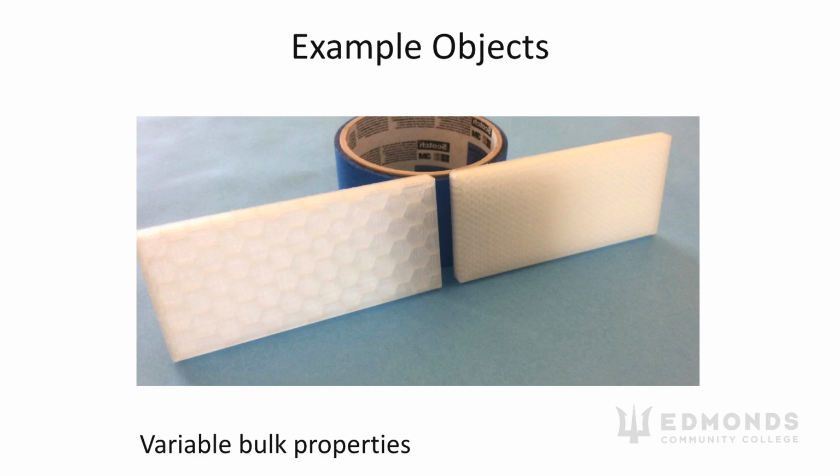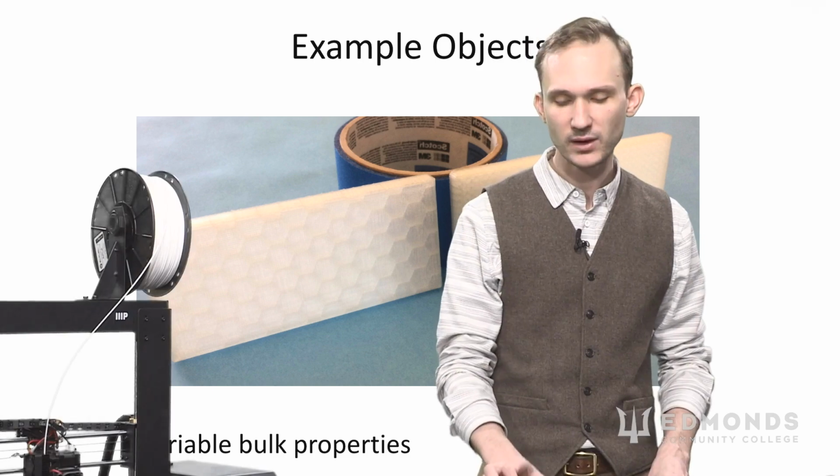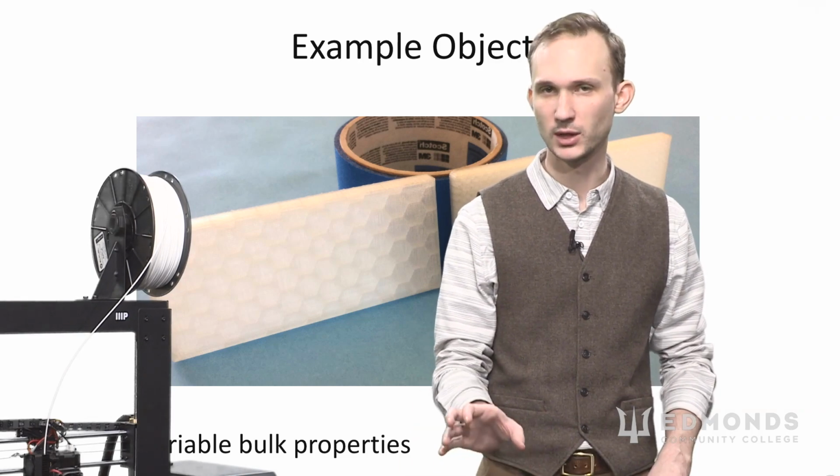So I could have a part here, for example, at a low density, that produces less stress shielding for the other materials that it is bonded to in its final application. A great example of that would be if we are using titanium femoral hip stems, with that prosthetic implant, we may want to have our component be as flexible as possible, even if the material isn't as flexible as we want it to be.